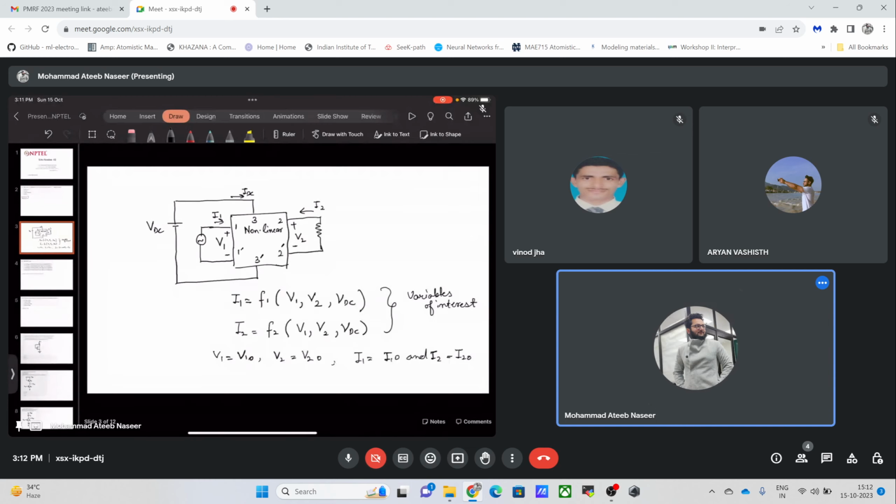For example, in case of a MOSFET, the bias determines whether the device operates in saturation, in the triode region, or in the deep off state region. There can be any region that this bias could drive this circuit in.